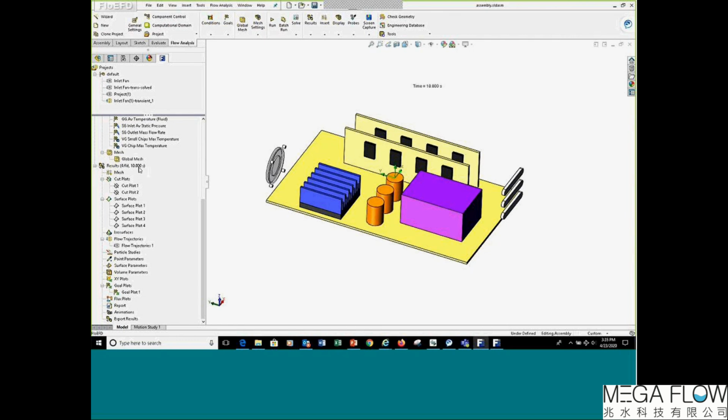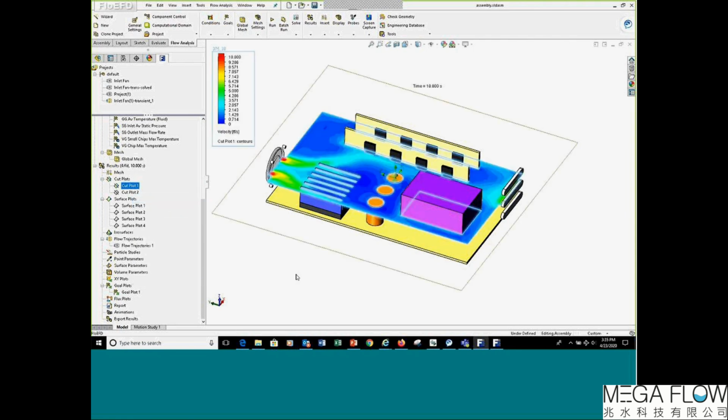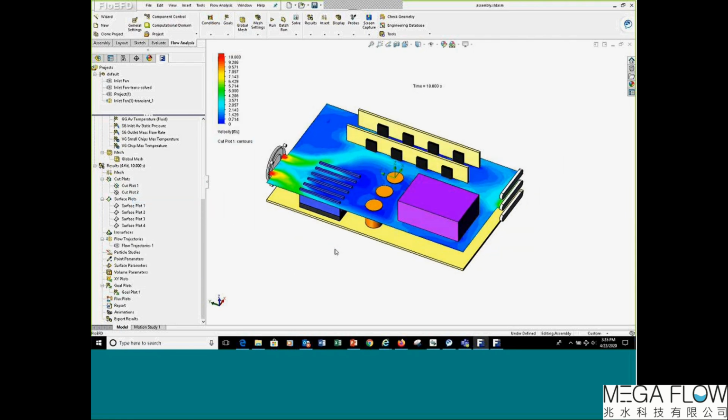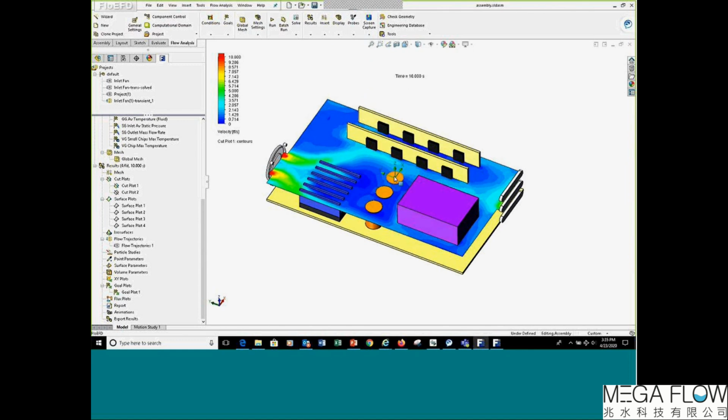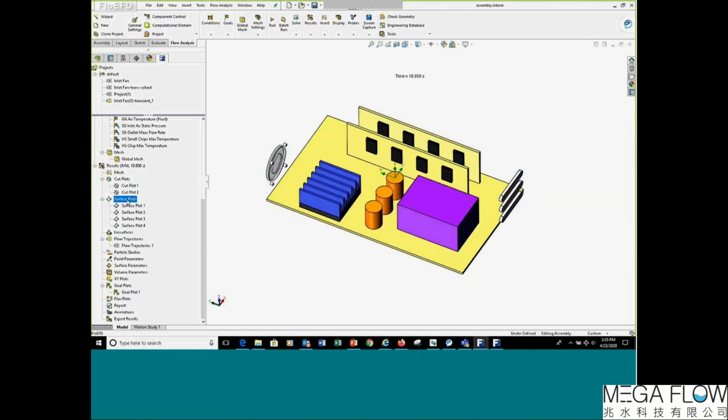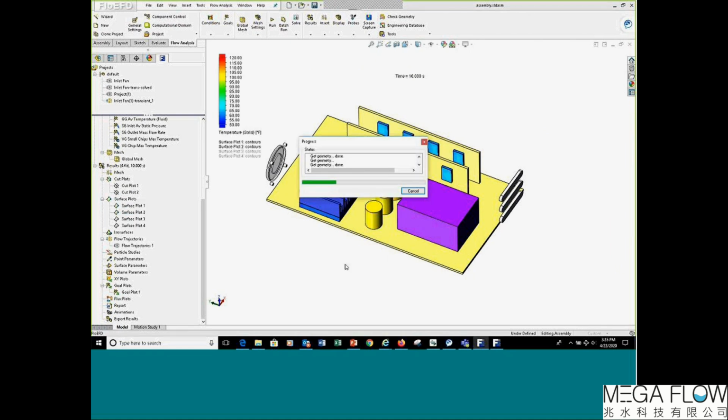It's at 10 seconds, and anything I do now, any plots that I create now, are representative of that 10-second timestamp, that time moment. There's a little timestamp in the graphic screen here, which is shown by going to display and time info. That's what makes that little timestamp show up. So again, any plots that I create right now are representative of 10 seconds.